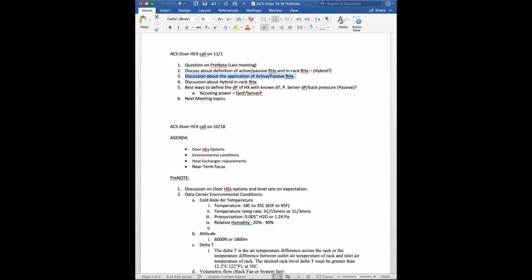Yeah, but if we look at the hybrid, to be honest, and let's say we catch 80% or something with direct chip cooling, and only 20% is left for conventional cooling, I would say, okay, that's relatively low power. Let's use traditional room cooling systems, CRAC systems, because to be honest, a back door system is more expensive. And the gain is that it can handle high amounts of energy for a relatively good solution with high temperatures and chiller-free solutions. But if it's only 20% you need to do, it's an expensive 20% to cool.